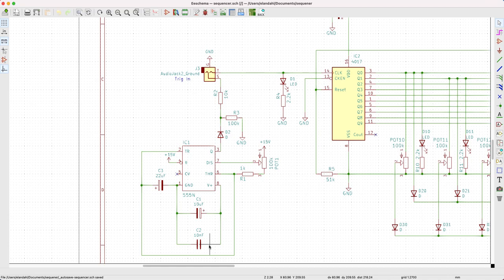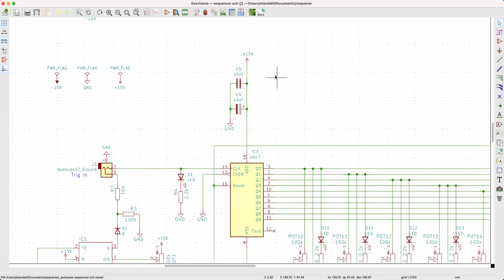early times in switching. And so this little solution you see is also used here on the power supply of the 4017 as well. So they bridge to ground. So any fast fluctuations get shorted out, allowing the DC voltage that goes through smoothly to continue. The same motif we saw in designing the main power supply. These particular capacitors should be placed as close as possible to the grounds and inputs of the device once we get to the PCB layout.